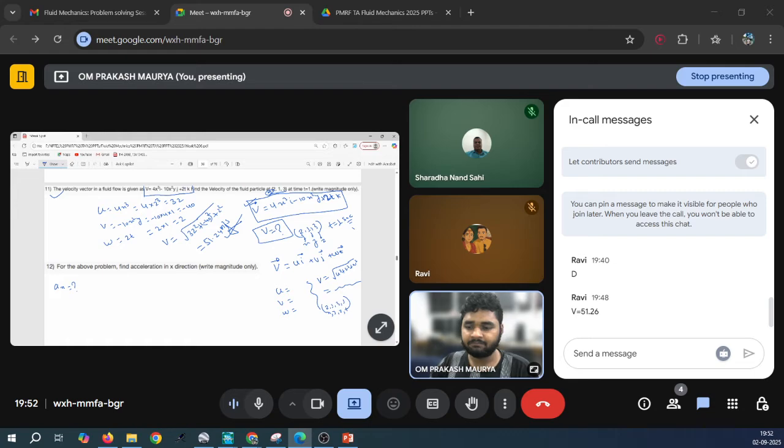Let me write it again. ax is equal to del u by del t, because in x direction you are considering u, plus u del u by del x plus v del u by del y plus w del u by del z.